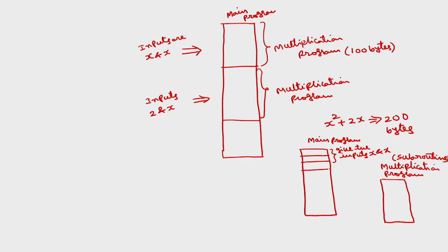Here we will call the multiplication program, and this is the starting address of multiplication. Whenever the call instruction is there, the microprocessor control goes to this one. Whatever inputs were given before will be multiplied, and the last instruction of any subroutine is return. This is RET, return.